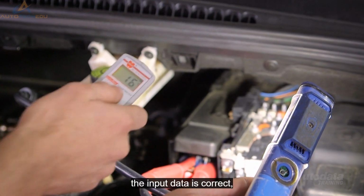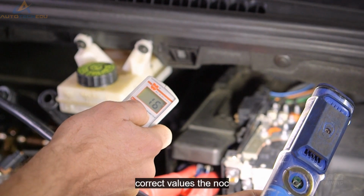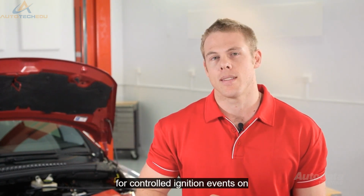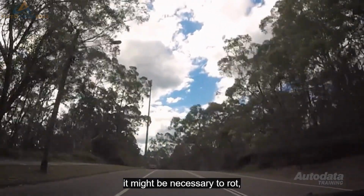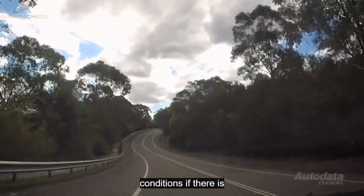If you're not sure if the input data is correct, use a thermometer to confirm the sensor is reading the correct values. The knock sensor provides vibrational information to the ECM for controlled ignition events. On a smaller capacity engine, the data would look like this: very minimal activity on a correctly functioning engine. Even when the RPM was increased, then snapped open, no real changes are seen. However, it might be necessary to road test the vehicle to replicate the engine's speed and load conditions.